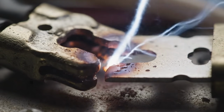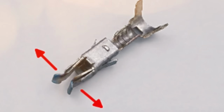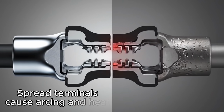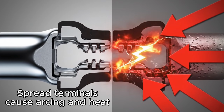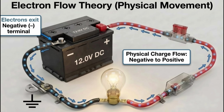That's what you're doing. Connectors can have the same issue. So if you imagine this is a connector, and I'll flash it up on the screen in a second. This is controlled arcing. This is fine. This is okay. But on a connector, it is not controlled. So that's a controlled arc. We're alright with that. We use that to ignite petrol in a cylinder. But on a connector, I'm going to show you now, it's uncontrolled arcing that causes a lot of problems and ultimately melted connectors.